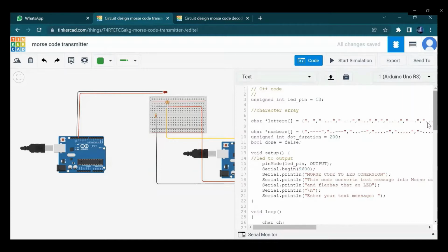The purpose of this project is to use embedded systems and the concepts of Internet of Things to build a model which not only converts user-prompted texts into Morse code using LEDs or flashlights, but also uses the LDR nearby, which receives the LED flickerings as input and translates the Morse code back into text and displays it on the monitor. This can make encryption and decryption very easy.